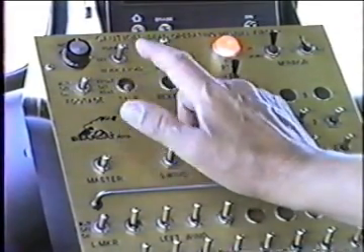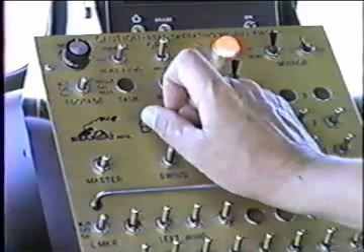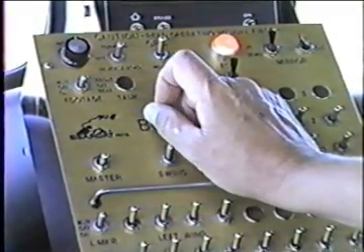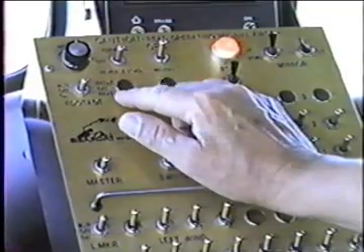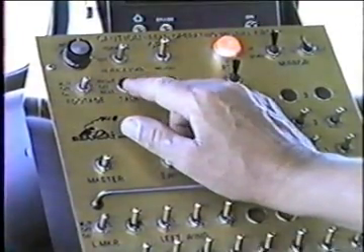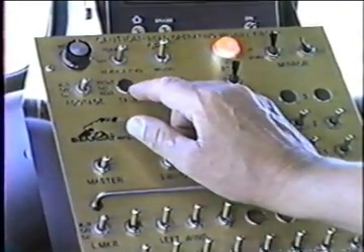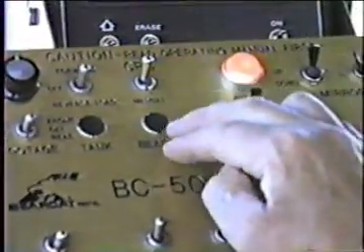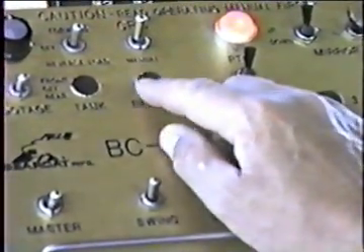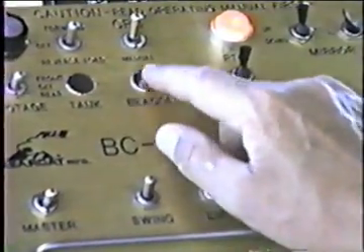That can be changed on the fly. If you're spreading and going uphill and you come over the top of the hill and you're fairly low in the tank, you should switch it right then over to the front suction so that as you're going down the hill, it doesn't lose suction in the tank. Last one here is just a beacon switch. This particular truck doesn't happen to have a beacon on it, so the hole is plugged.